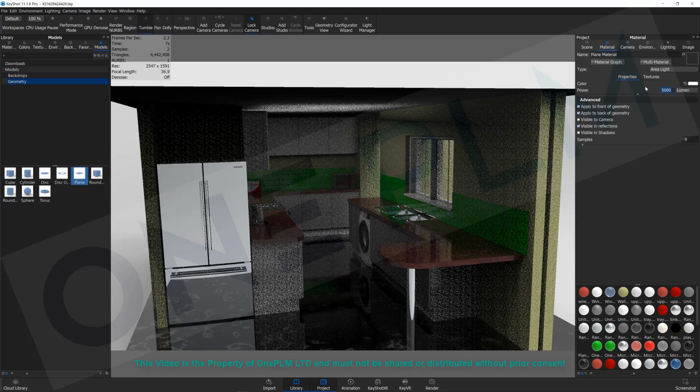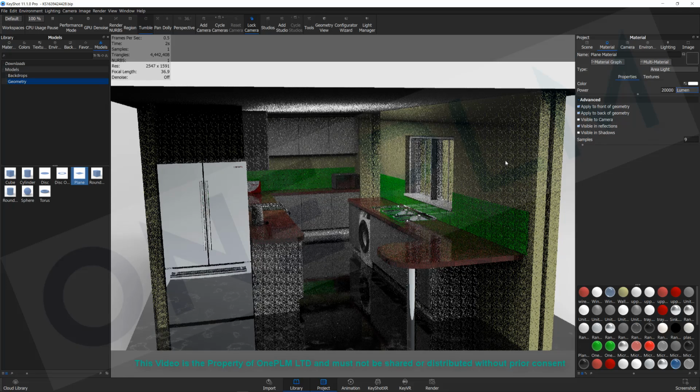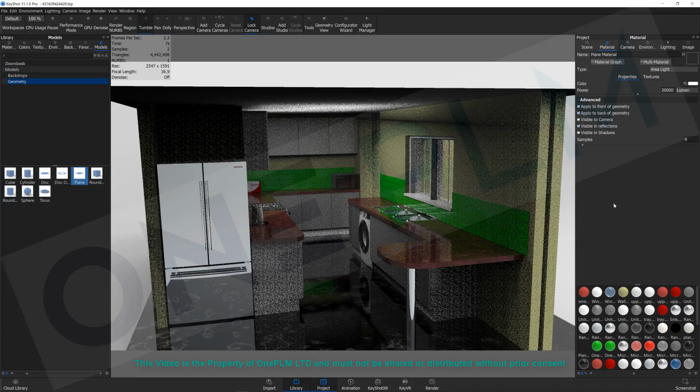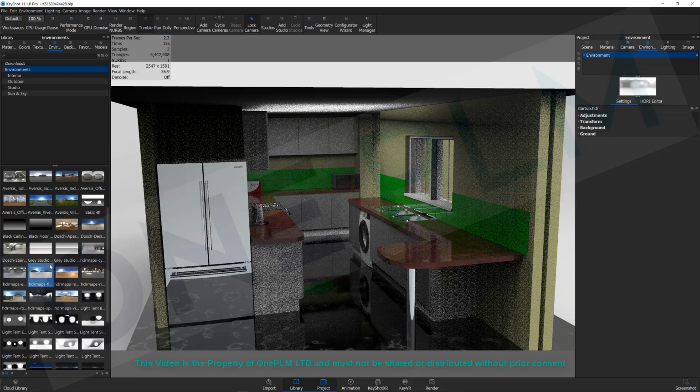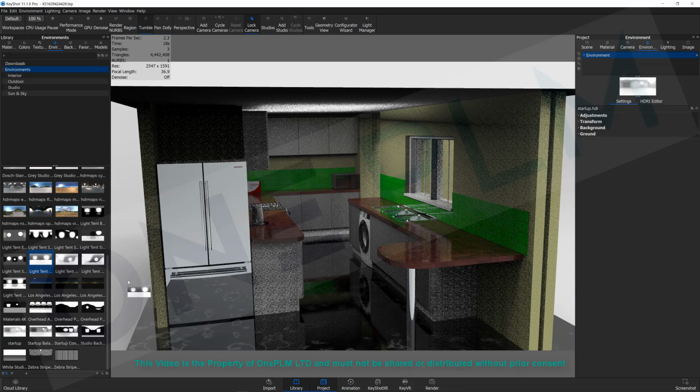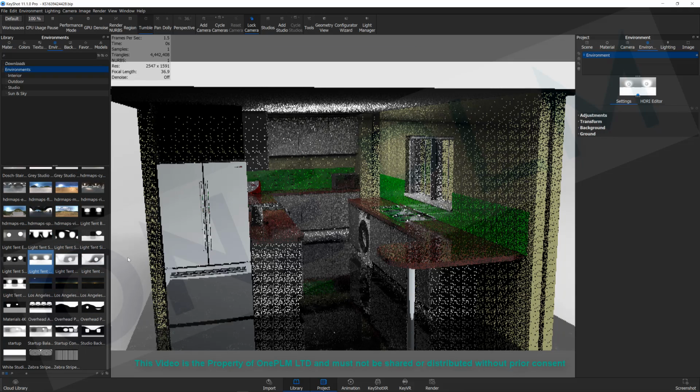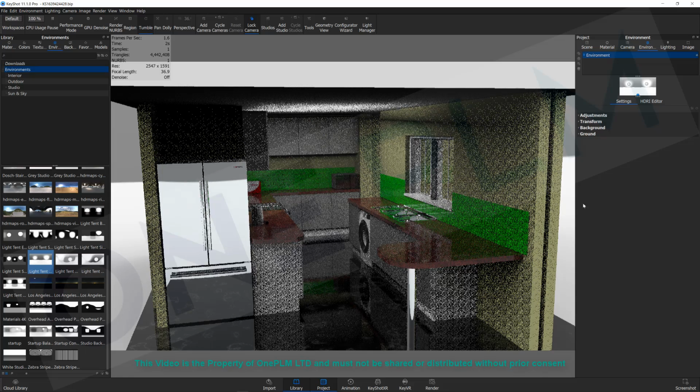So we can move that plane around. We can move cubes to get the lighting how we want. So I'm just going to go to 20,000 on there. That's going to brighten our scene up quite a bit. We can add other things. So currently we've got an environment on here, which is kind of a lighting environment. So if I choose on here, we can choose the appropriate environment that we want. So we can drag this into the scene, and this is going to decide on the reflections that we've got on here.